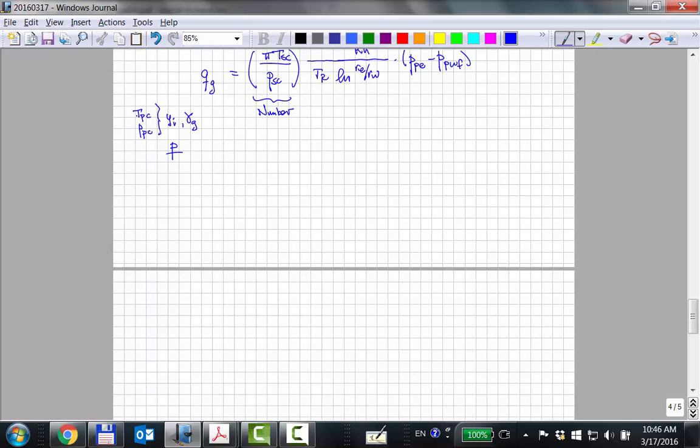You have an estimate of the pseudocritical pressure and temperature of the gas. And then from your initial reservoir pressure down to 1 atmosphere, you tabulate mu, Z, like that. You calculate P over mu Z times 2 in a column, and then you just do a simple integration, trapezoid or whatever you like.